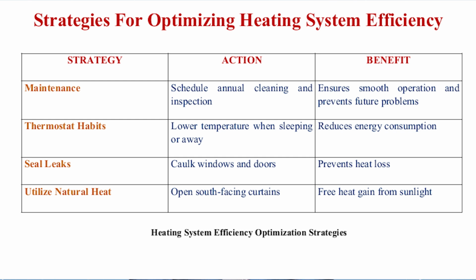It needs regular maintenance, clean or replace air filters. A clogged filter restricts airflow, forcing the system to work harder. Replace air filters monthly during peak heating season. Inspect and clean components. A technician can identify and address any minor issues before they snowball into bigger problems.